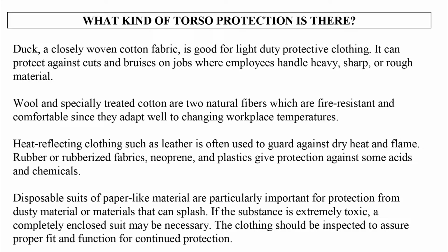Heat-reflecting clothing, such as leather, is often used to guard against dry heat and flame. Rubber or rubberized fabrics, neoprene, and plastics give protection against some acids and chemicals. Disposable suits of paper-like material are particularly important for protection from dusty material or materials that can splash. If the substance is extremely toxic, a completely enclosed suit may be necessary.